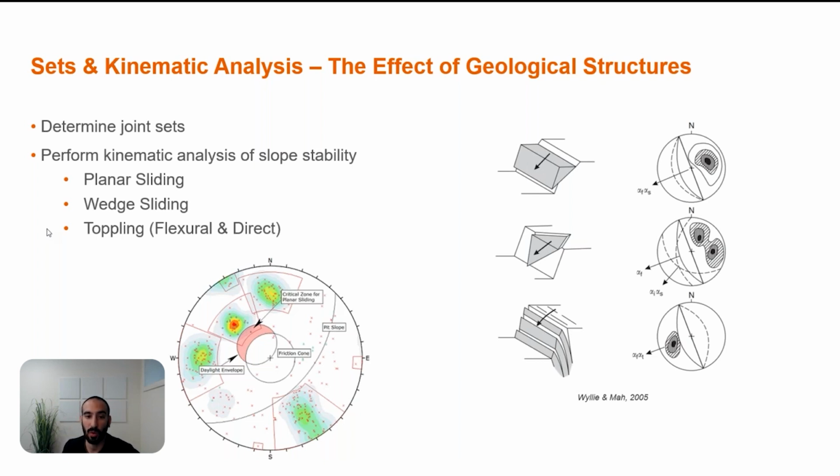And almost all rock slope stability studies should address the structural geology of the site, and such studies usually involve 2 steps. First one is to determine the properties of discontinuities, which involves mapping outcrops and existing cuts, if any, as Markus showed us a few minutes ago, and examining diamond drill cores.